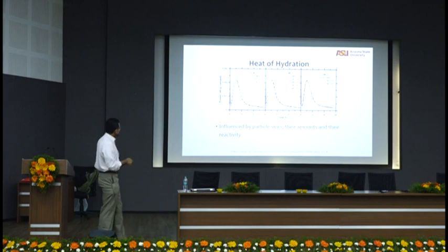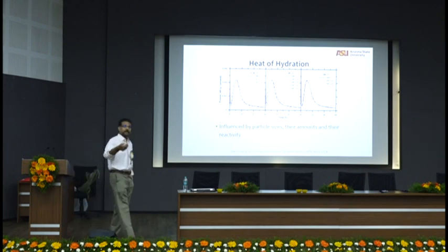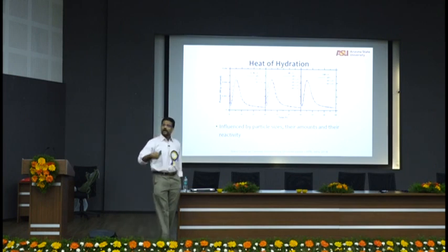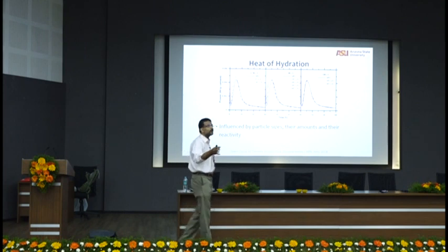Whereas if I want more heat of hydration, if I have a cold weather concreting, I can use this technique with reduction in cement. So basically my argument here is, you don't have to increase cement content just because it is cold. You see this all the time.